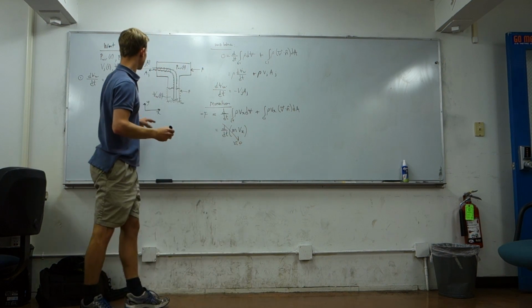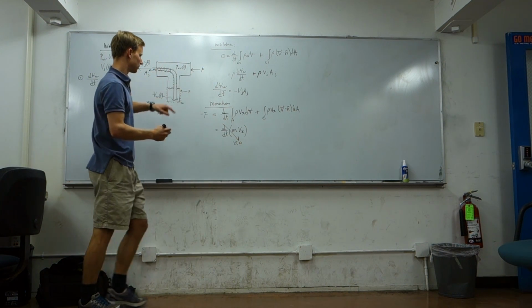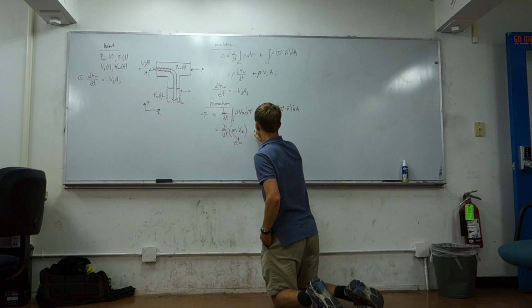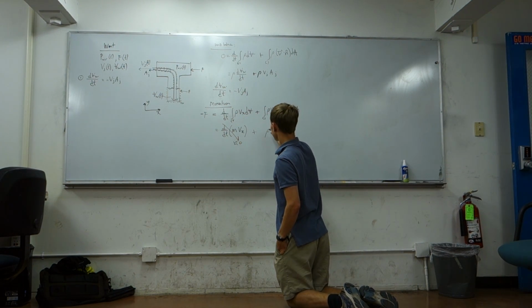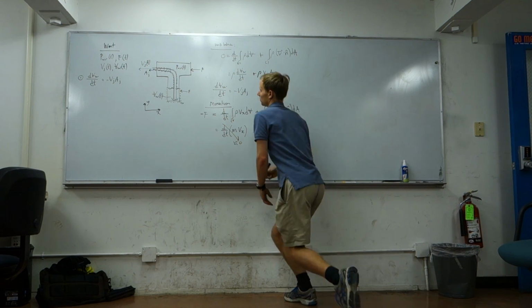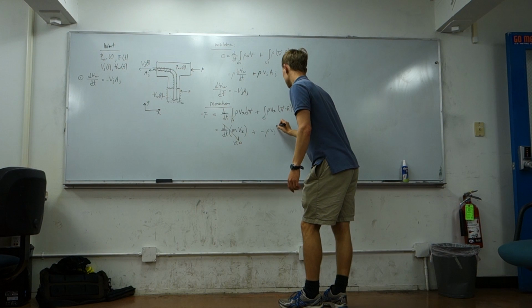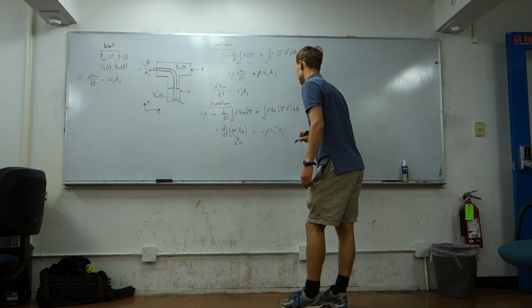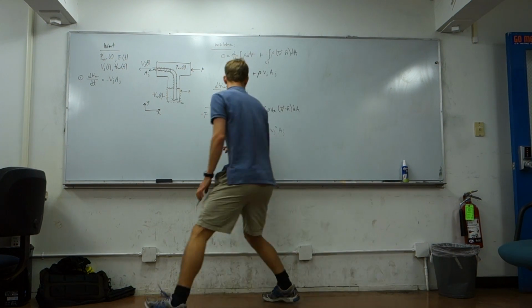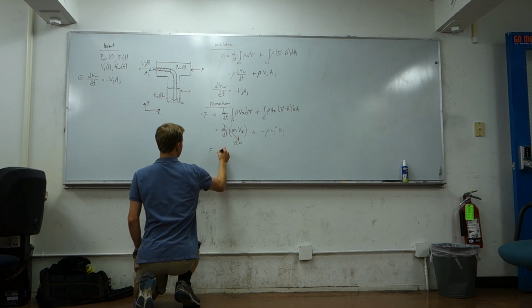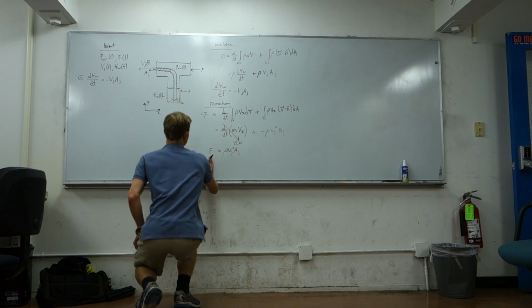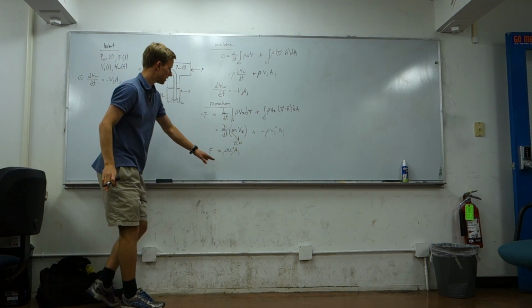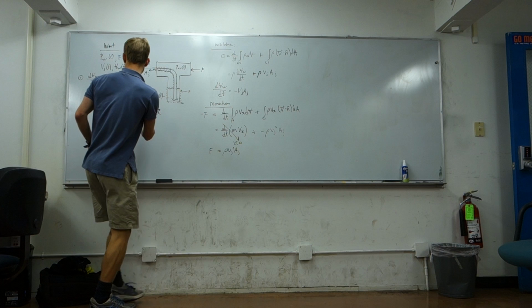Now the flux term, we'll do this real quick. We have our rho. Our Vx right now is in our negative Vj term, so I'll put a negative out in front. And then our V dot n is again positive Vj, so that's a Vj squared, and our Aj is there. So we're left with the thrust force is equal to rho Vj squared Aj. Sorry, this is a reaction force to counteract the thrust. It is rho Vj squared Aj. So that's equation number 2.